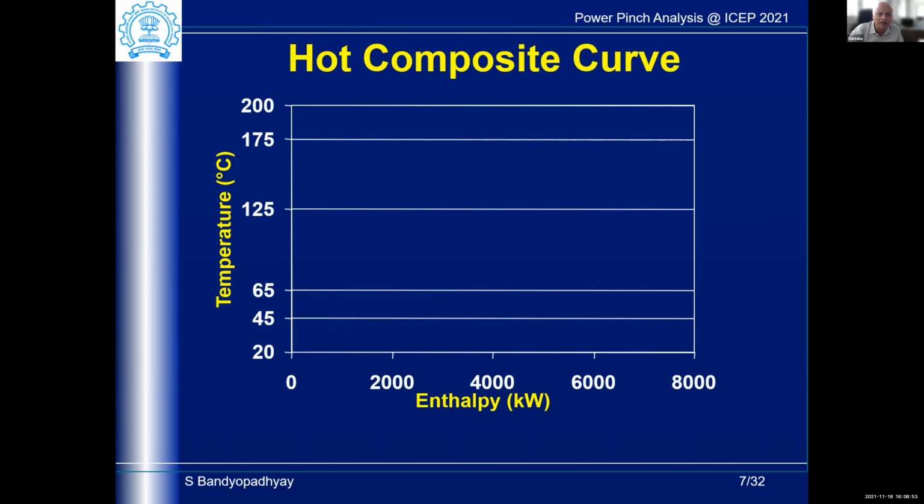So if you look at H1 and H2, we can draw them in temperature, enthalpy. Enthalpy is not the correct word, it should be heat duty. Enthalpy and heat duty diagram. Again, temperatures are fixed. This enthalpy or heat duty is relative. That means we can look for the difference between starting and ending and say this much amount of heat duty is available. Now, if we add them thermodynamically, then we'll get a curve like this, where the first part is